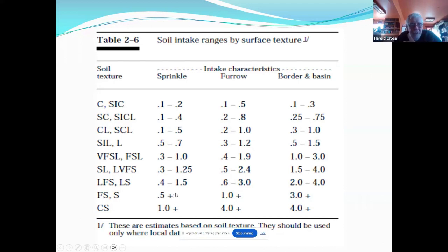So that all plays together: the soil type, the infiltration rate, the water holding capacity of that soil. You're beginning to see kind of a process that you go through to think about these. And I can't overemphasize the necessity to look at all these and be able to talk to this subject at your first meeting with a grower. You do your homework, pull up the soils, have them give you the location of the farm, pull the soils map on those, and look for those critical factors that could be restrictive or create management problems down the road.